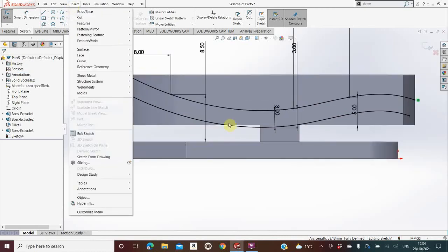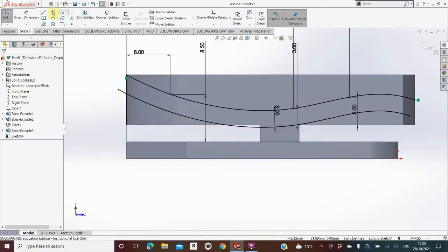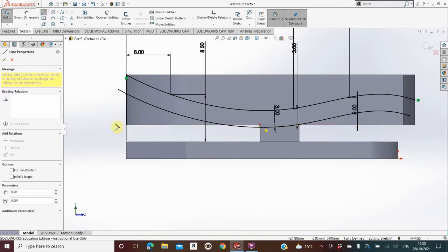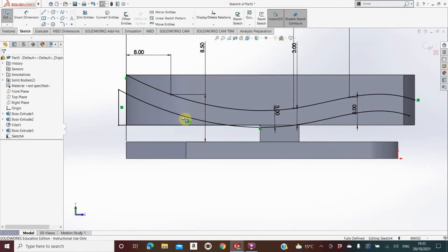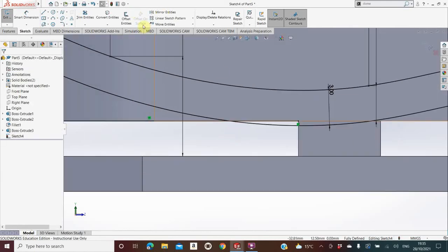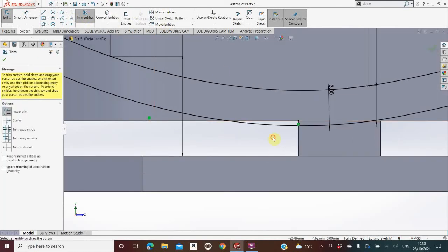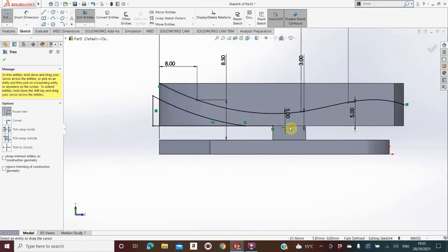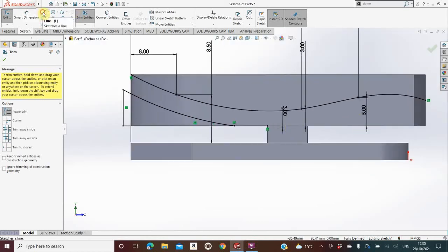Now, what we have to do next is go to Line, and I have to draw a line that goes from, we'll say from this corner here, on out here, some sort of a distance. Make sure you go past it, to pick up the one above it, and then I click straight up, and I push escape. And we're going to go to Trim next. I'm going to trim away this here, don't need it. That's good. And then finally, I'm going to go back to Line again.